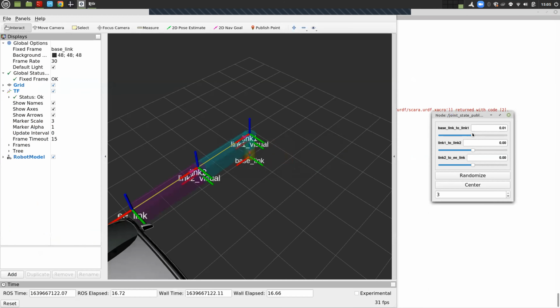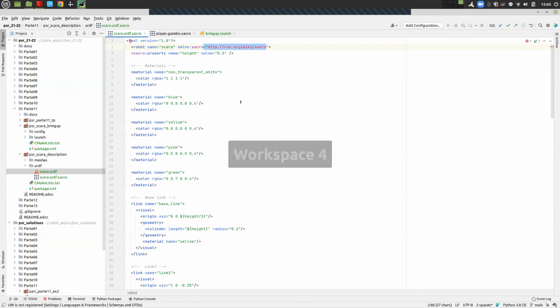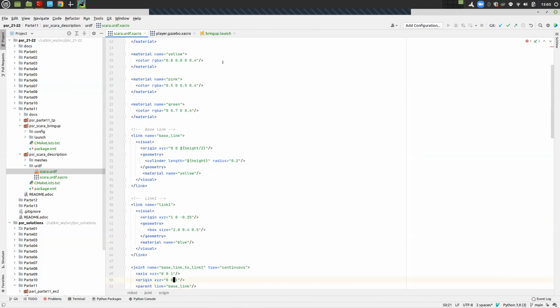No problem. Okay. So Xacro is useful for defining variables, for doing some math, and even for including other Xacros. So with Xacros, you can have a hierarchy of Xacro files. You can split a single file into many and include them, like the launch files.